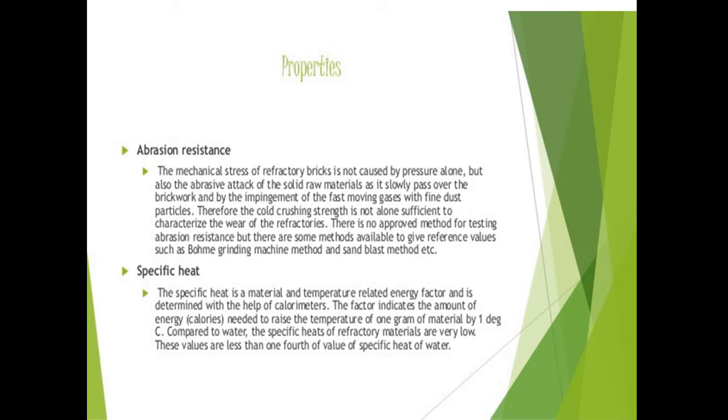Abrasion resistance. The mechanical stress of refractory bricks is not caused by pressure alone, but also the abrasive attack of the solid raw materials as it slowly passes over the brickwork and by the impingement of the fast moving gases with fine dust particles. Therefore, the cold crushing strength is not alone sufficient to characterize the wear of the refractories.